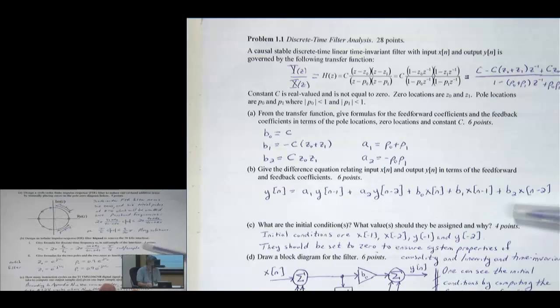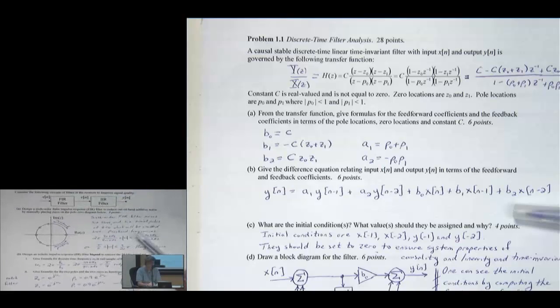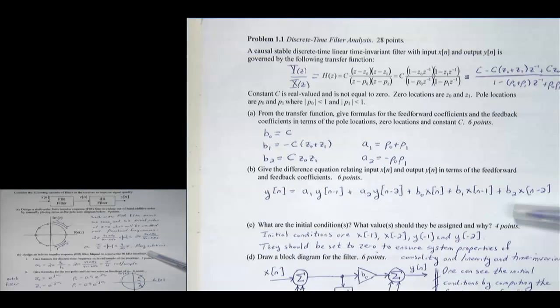Okay, so this was a lot like previous tests. I have an FIR filter, which is our bandpass filter to attenuate out of band noise. The IIR filter is going to be a notch filter to remove this 50 kilohertz interferer. This is a real interference source. It turns out in power line communications, we get a lot of interferers in the 20 kilohertz to 100 kilohertz bands. They have to do with amplification in the ballast of transformers. Basically, any DC to DC converter, buck converters give you these kinds of harmonics. They're in many different power systems in a house.